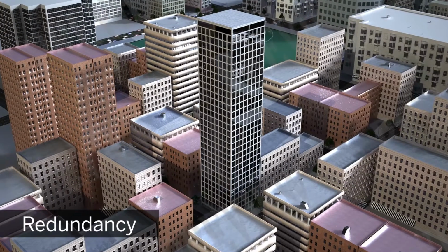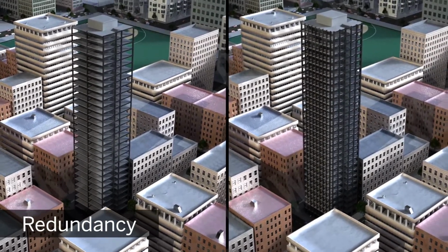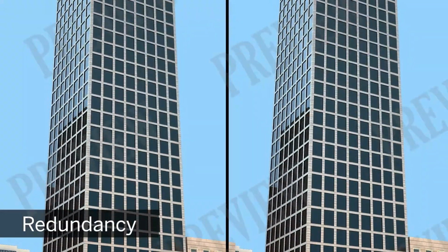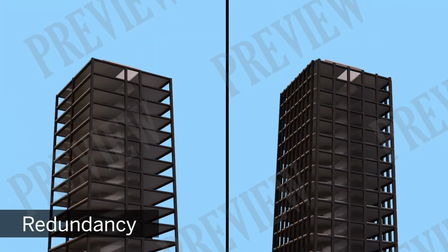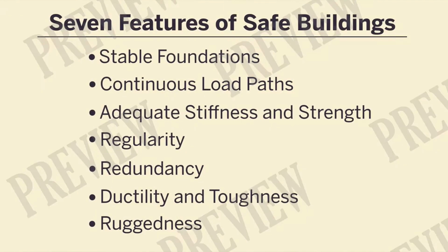If all of a structure's strength and resistance is concentrated in only one or a few elements, the structure will not have the necessary residual strength if these elements are seriously damaged, and it could collapse. If a structure is redundant, a relatively large number of elements participate in providing a structure strength, and if only a few are badly damaged, the remaining elements should have adequate residual strength to prevent collapse.